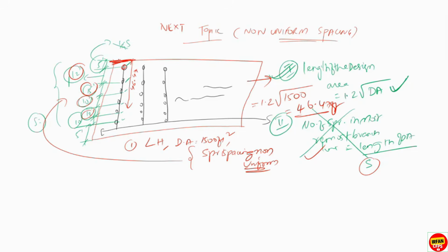Okay, you already know this. We need to draw from here itself, from the remotest sprinkler, and extend this parallel to the branch line. So we need to measure 46.47 feet from this point, right? And now, how many sprinklers are covered in 46.47? This is the point. So 1, 2, 3, 4. Assume that the 46.47 is still here. So you'll consider 1, 2, 3, 4.